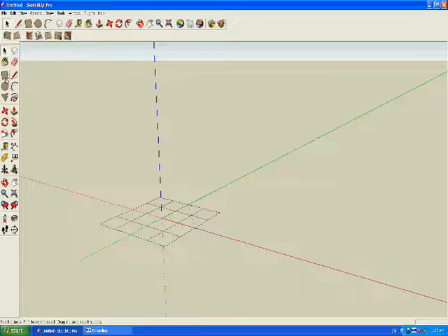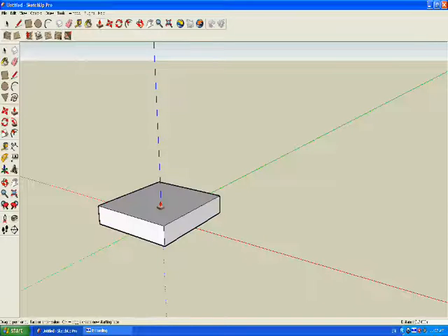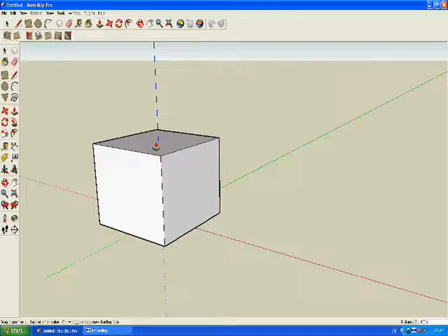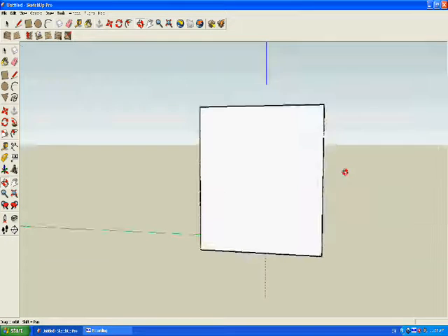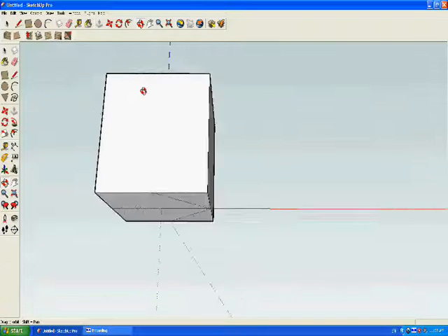Now, to build my cube, I'll start by drawing a square at the base. I'll just lock it to each corner of the boundaries. Now to turn it to a cube, I'll extrude it to 4 meters. There we go, now we have a fully functional 3D cube.